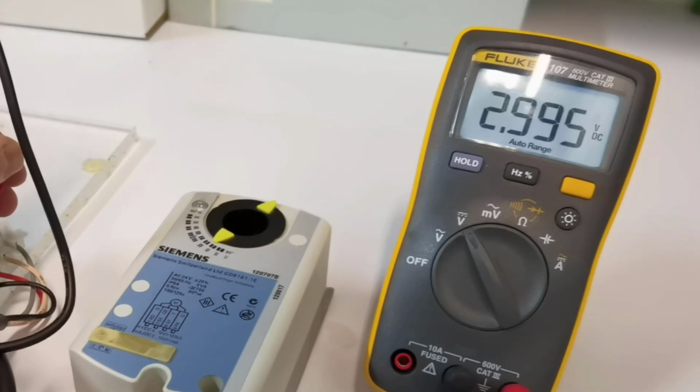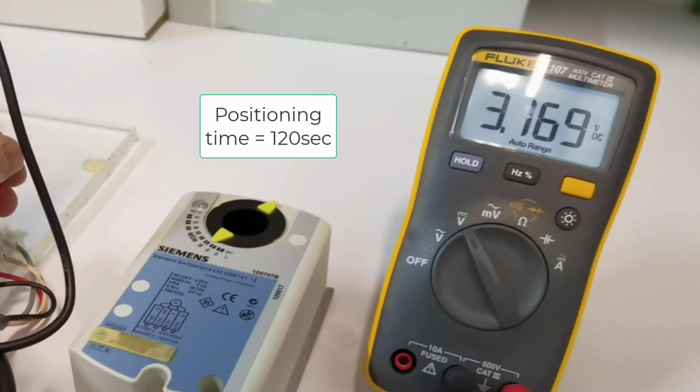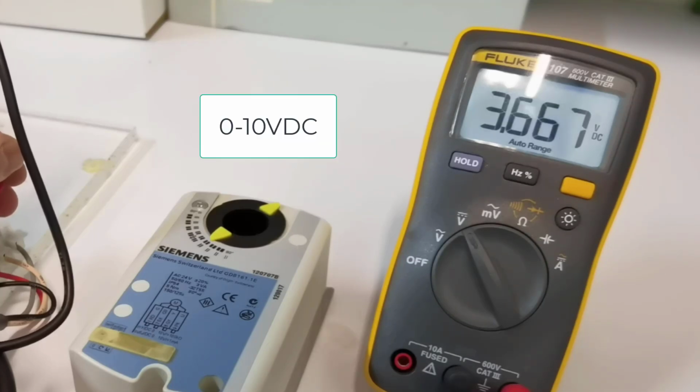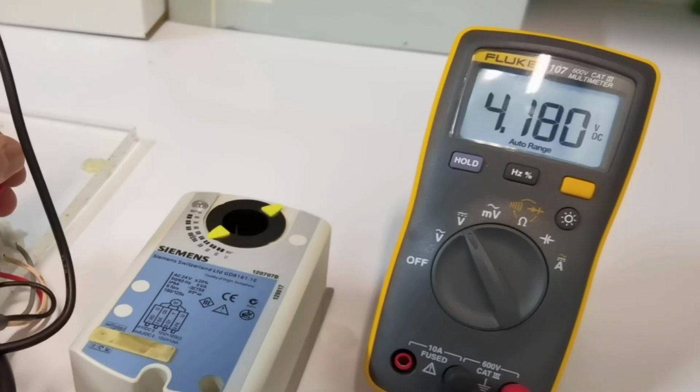The positioning time of this actuator is approximately 120 seconds, and the signal voltage is 0 to 10 volts, meaning at around 10 volts the actuator is in 90 degrees rotation.